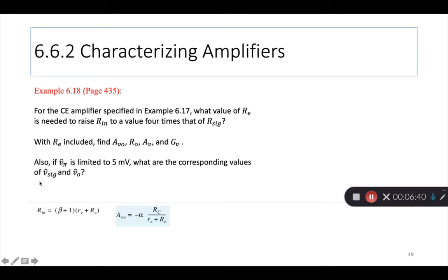That means you can apply a larger voltage swing on the V signal and still not drive the transistor into saturation. So that's the benefit, right? The output voltage stays about the same because the gain falls when you introduce an RE, but the advantage is it's more stable.